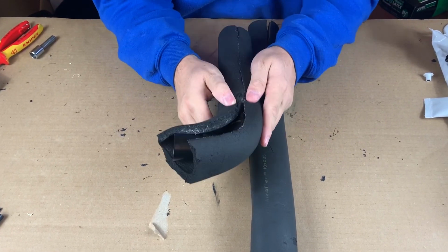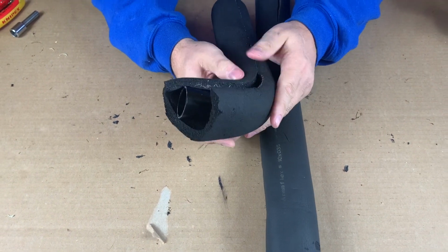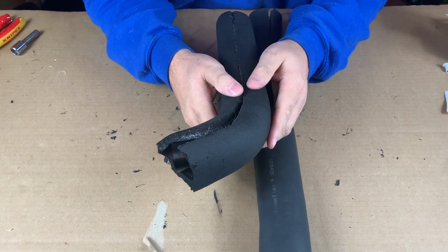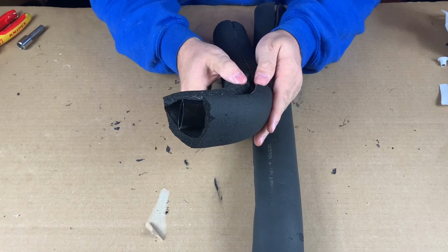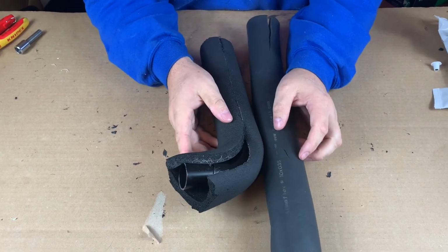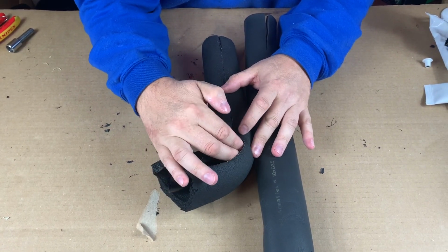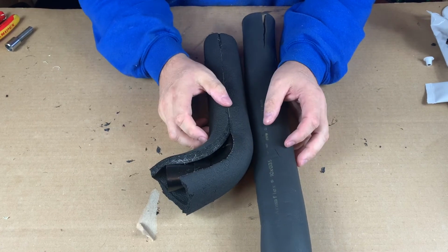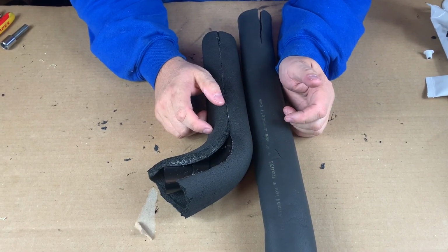Then there's the other type of Class O, which is the self-sealed type, and this starts to come apart when it's really hot or when it's really cold, or it gets any moisture in it. And the big problem that we have is we can't let any moisture or water get inside this lagging or any other lagging, because then it'll just become a fridge and it's useless.